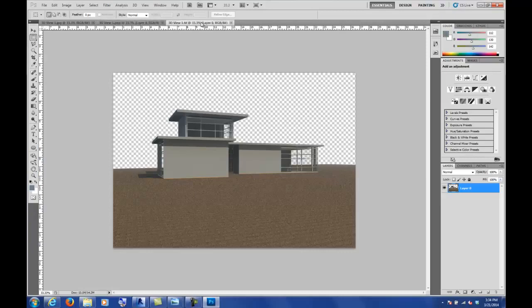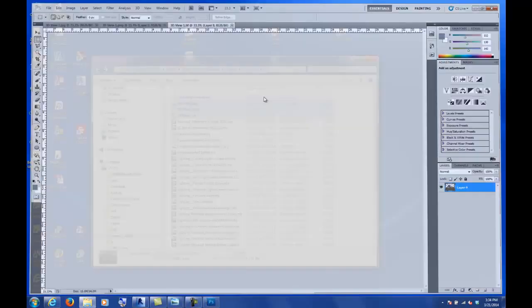The TIFF file does the same thing, so the TIFF and the PNG are kind of exactly the same. So obviously the TIFF files are probably preferable when you start working in Photoshop and adding more to it and so on. So those are your image options. So again, obviously if you don't like the Revit sky, you can go ahead and insert your own, but make sure you save that as a TIFF or a PNG to get that transparency. So I'll close out of that.